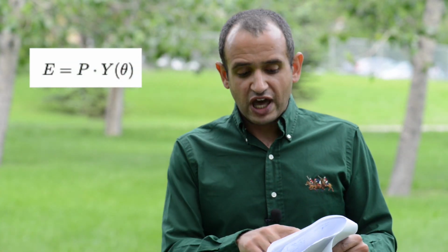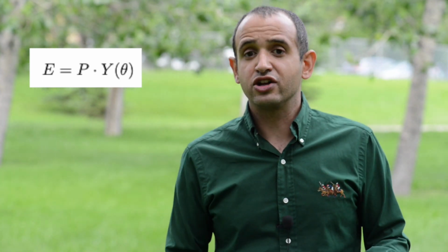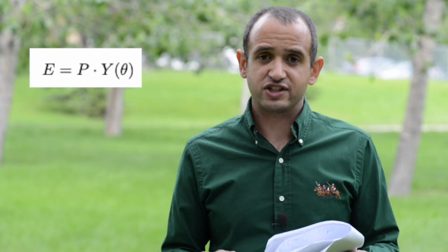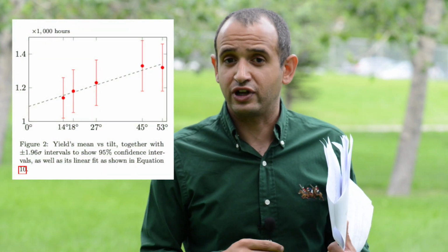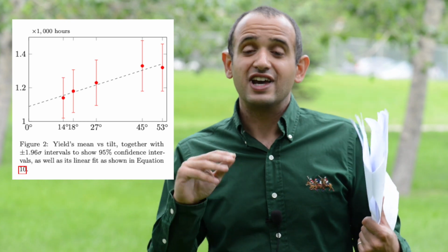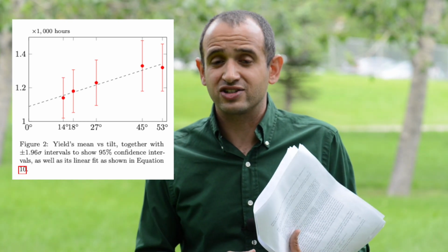Whatever we do, we have to make sure that our system produces a certain amount of energy E. The higher the P is, the lower the Y can be, and vice versa. As I mentioned, an array with an optimally producing tilt is a tilt that is equal to or slightly less than the latitude value. For example, at NAIT, the 45-degree module produces just as much energy as the module with 53 degrees, which is the latitude value for Edmonton. That is because silicon solar modules are just better at capturing high light intensity than they are at low light intensity.